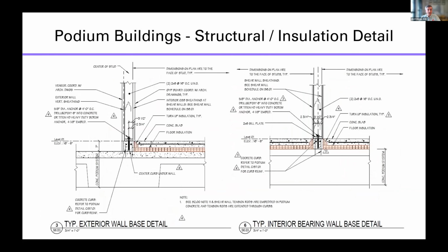And finally, I was asked to talk about podium buildings because we see a lot of them going up now, where you have a steel or concrete platform where you build maybe a 5 or 6 story tall wood framed stud wall residential building. You have to separate the conditioned space from the unconditioned space below, like for parking.